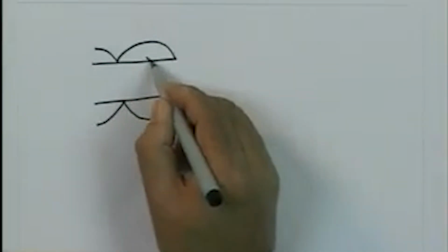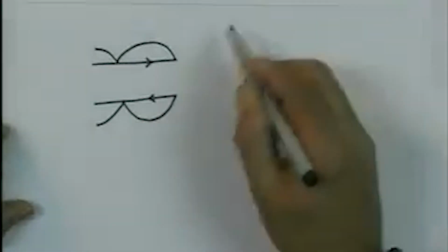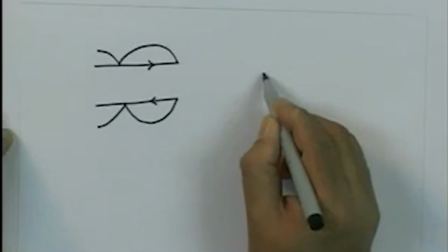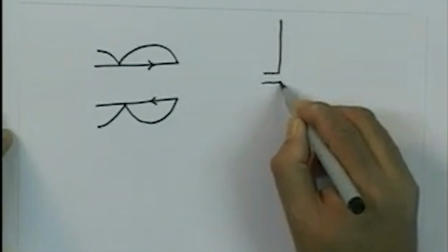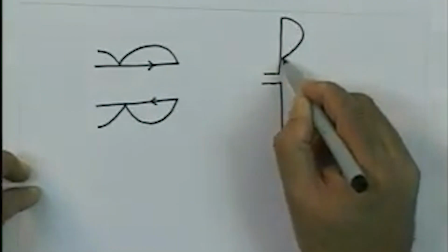If the current is flowing this way here, the current will be flowing in the opposite direction on the second wire. Now, if you slowly flare up, so that ultimately it becomes a completely opened up version, which is the dipole, then this can be visualized as a flared up version of this transmission line, and the current distribution still, if we say, is this.